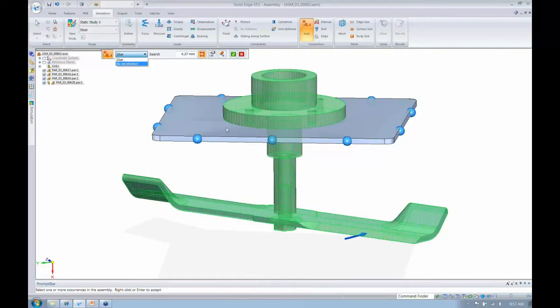What glued means is those elements that lie in contact on these two surfaces, for example, have to move together. So their motion in the X, motion in the Y, and motion in the Z is equal. They are literally glued together. They can move, but the nodes have to stay together. No penetration means this part could slide relative to the other, or it could come off the other part, come apart. It just can't go down through the part. It can't penetrate into the part. I always start with a glued connection. If you need to make it more complicated later, you can do that.